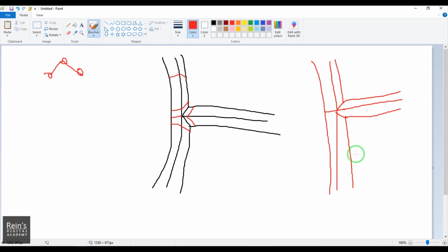Now this is perfectly okay, but the problem is when I apply mesh smooth, the roundness goes a long way, and I don't want that. So that is where I'm going to put a crease line for this, so that it preserves that corner. And here also I'll put a line, and here also I put a line. So this is how I plan my corner loops here.